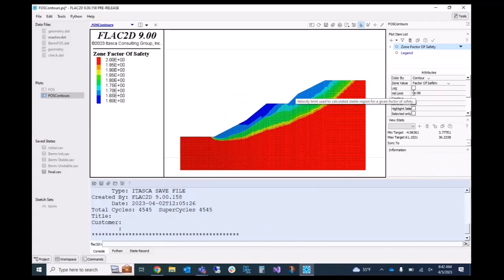It's kind of arbitrary, so you can actually change this number, and you get slightly different answers. I don't really have super good advice as to what number you should use there, except I always just use the default. Again, it's not super duper accurate, but it does give you some idea of multiple different possible failure surfaces, and roughly what their factor of safety would be, if that makes sense. It's just kind of a handy fun thing you can use to look at these things in a little bit more detail.